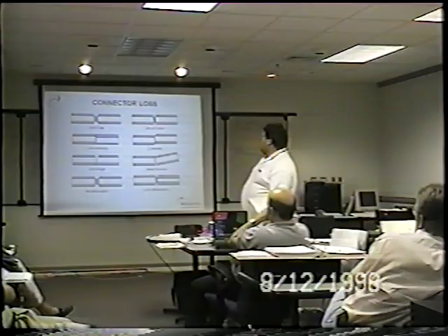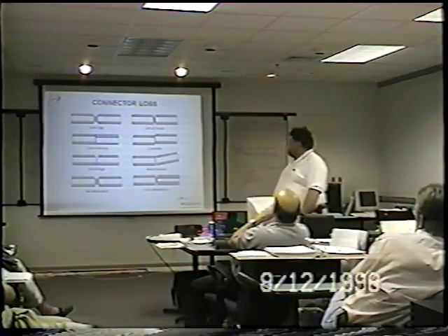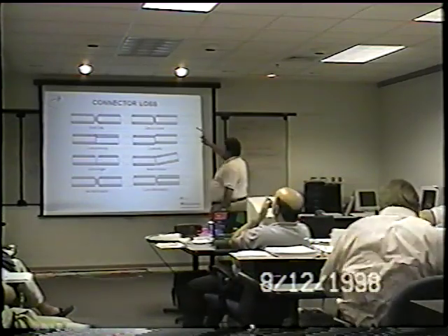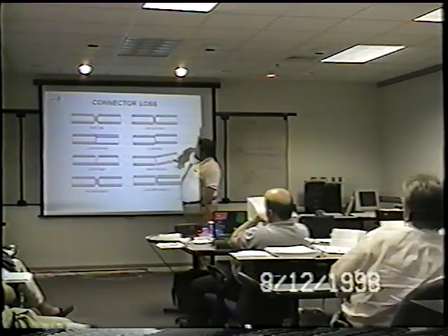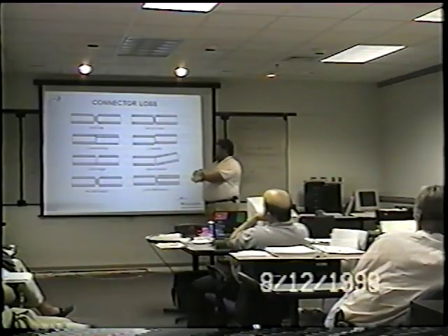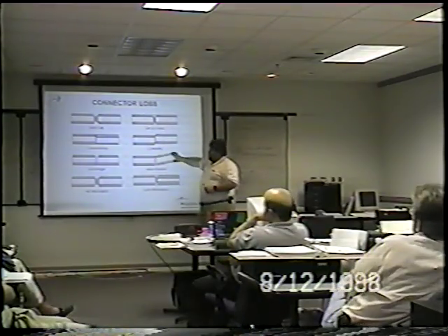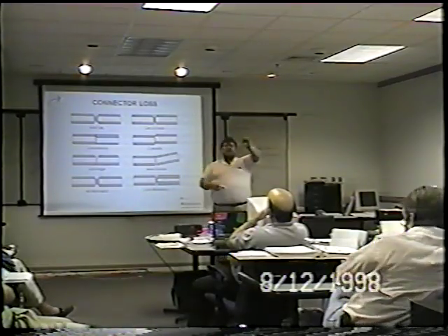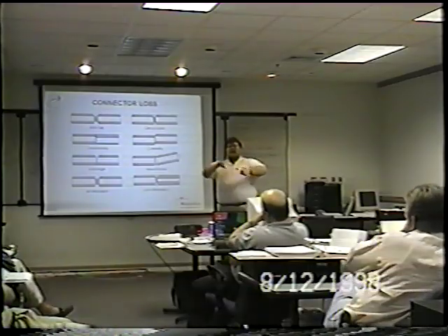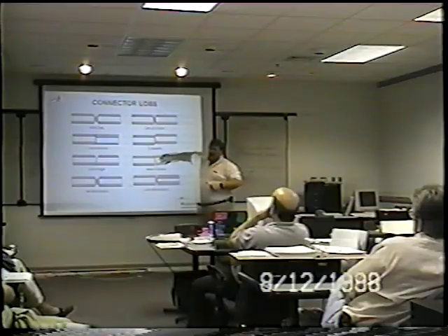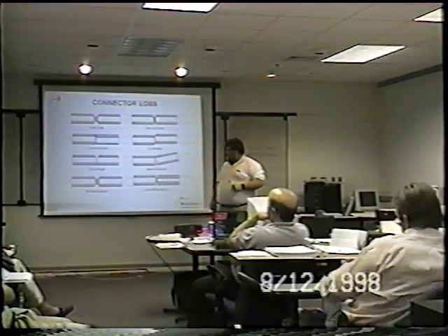Let's blow ahead a little bit. Here are some other loss contributors to connector issues. Here at the end is the number one cause: dirt and finish and crud. Alignment issues, coaxiality, axial runout. You've got bending of the fiber. This is typically caused by not dressing the fiber out of the rack coming out of the customer equipment. You roll it up in a roll, and let the weight of that roll tug on the fiber, and this will result in basically axial runout of the fiber itself.